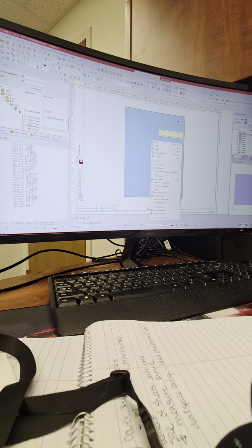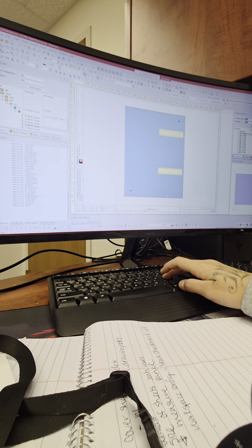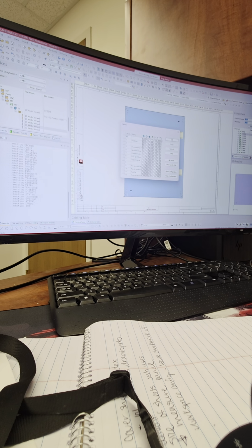Then how do you bring it back? If you want to bring it back, right click on the background, anywhere in the background. You don't even have to click on anything, as long as you're on the sheet. Press L on your keyboard for levels, just L for levels. These are all the 255 layers that you can scroll through. Everything with text is what you were able to see in the drop down menu that you just used. And if you scroll all the way to the bottom, there's your hidden panel 254. So if you enable these two checkboxes, one is for objects, one is for symbols.